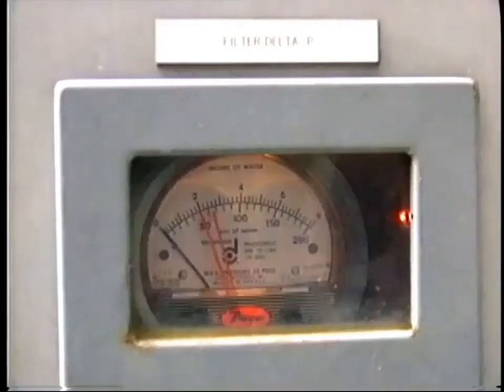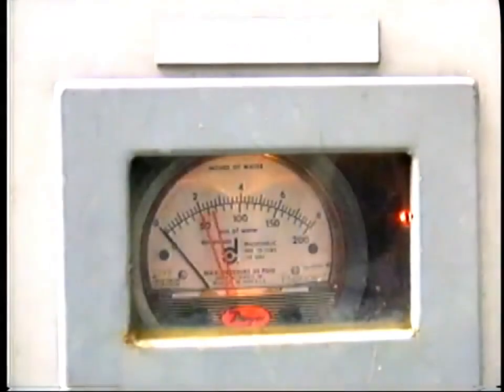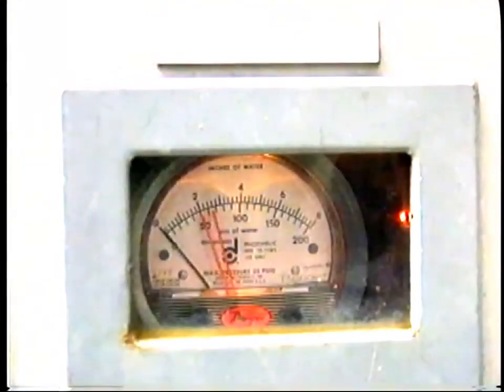As we can see, this system is self-contained and requires no attention from the operator other than to ensure that the filters are clean, thus allowing sufficient air to pass. The pressure drop across the filter will indicate when it needs to be replaced. On standby or peaking units, this task can easily be performed when the unit is out of service.